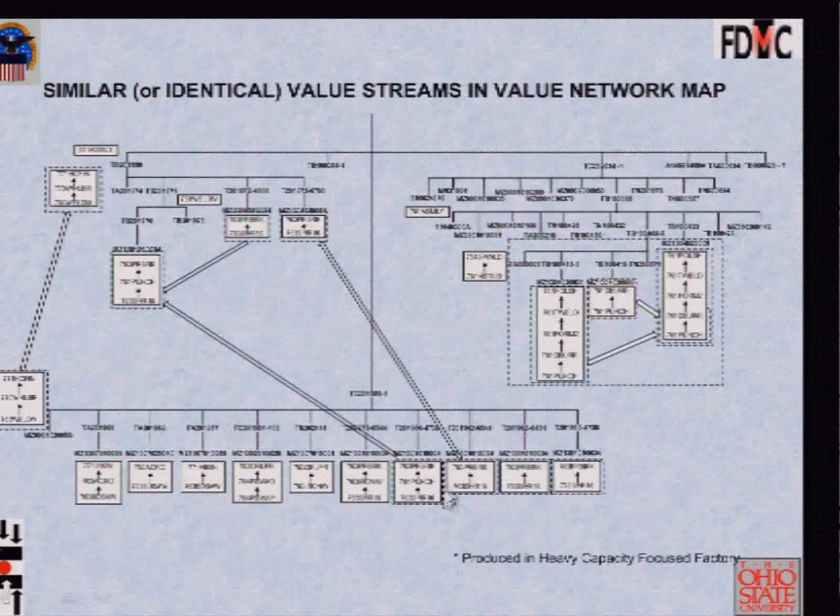So, just to point out again the difficulties which arise when there are similar or identical value streams: just because there are value streams in this subassembly which are identical to value streams in this subassembly does not mean you merge them. Now, there are two schools of thought. One school would say, design mini factories, one for each of these 3 sub-assemblies. But then you duplicate equipment. Another school of thought would be, no, create flexible cells. When there's a request for a particular product, each of these cells will be told, make the following components, even though the components will go into separate sub-assemblies.